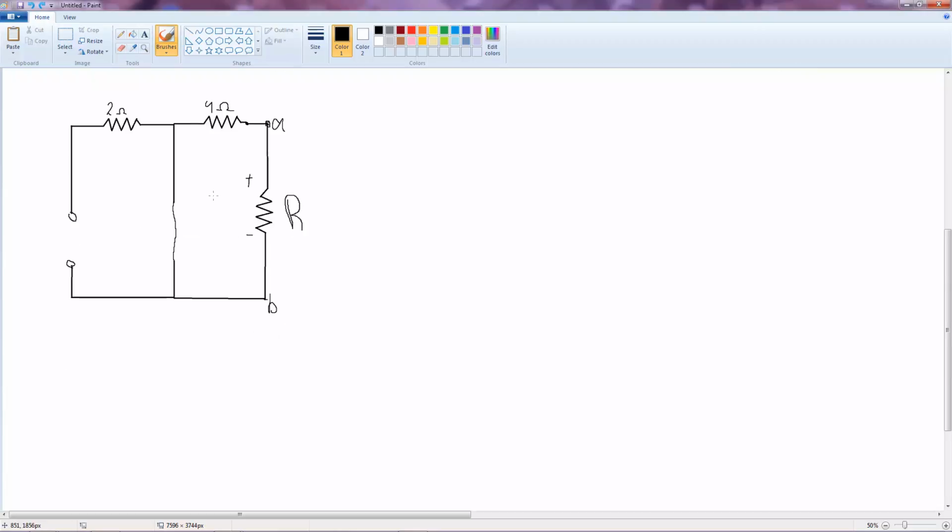But in this case, as the circuit is super mega ultra simple, R Thevenin will be 4 ohms, since if you put a load here, the current will go like this, and it will never come here, since we replaced the current source with an open circuit. So the current can't just do something like this and appear here and continue.